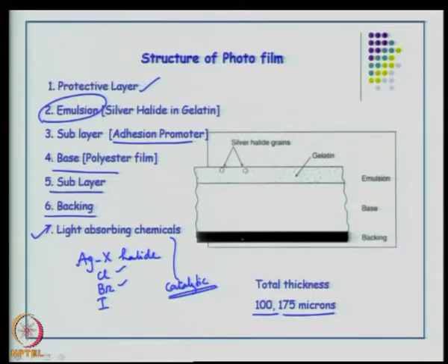So, this process has to propagate through the entire silver halide material that is embedded in gelatin and that is very uniformly spread in your photographic film. So, this will cause changes chemically and physically also, you will see changes in the color. So, that is the basic chemical process that you are seeing when you have the light exposed in the photoplotter to the silver halide film.